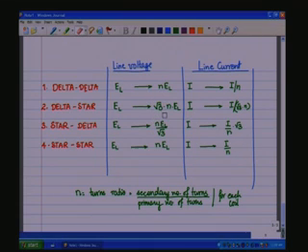So the line voltage is actually root 3 times the phase voltage, and therefore the coil differential voltages are going to be a factor less by root 3, because the line voltage on the secondary star connected is going to be root 3 higher.